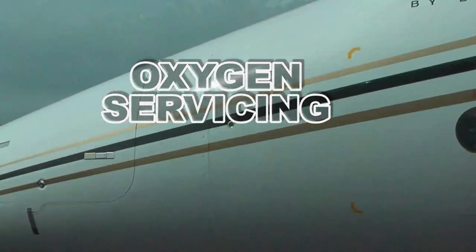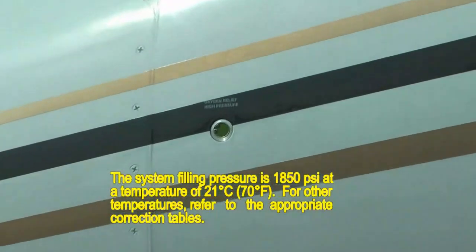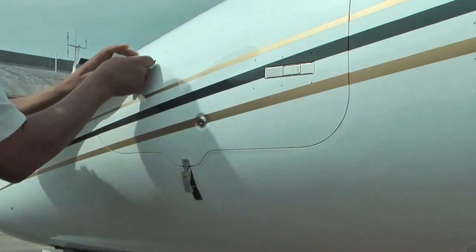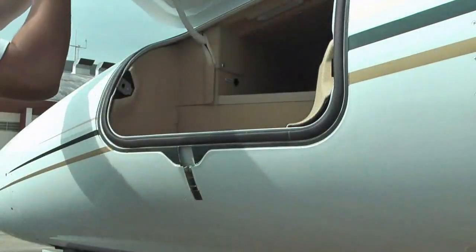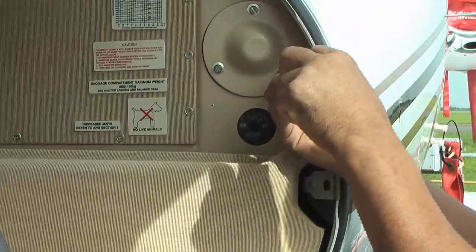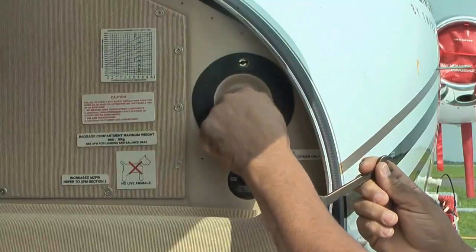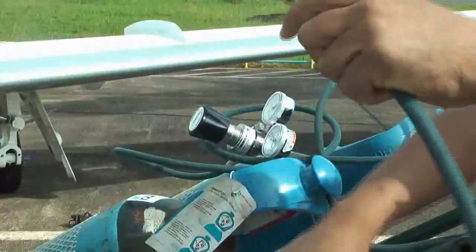Oxygen servicing. Filling operation is carried out as follows. Check the overboard discharge indicator to make sure the oxygen has not been discharged. Open the oxygen compartment door. Remove the protection cap from the fill valve. Connect the pressure oxygen servicing regulator to the oxygen source.